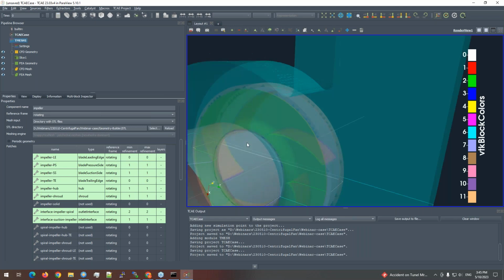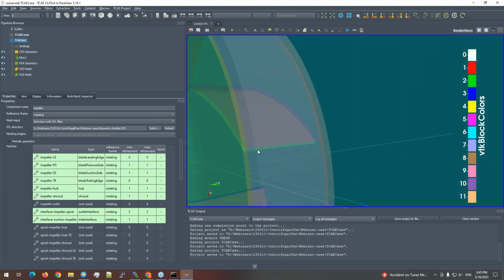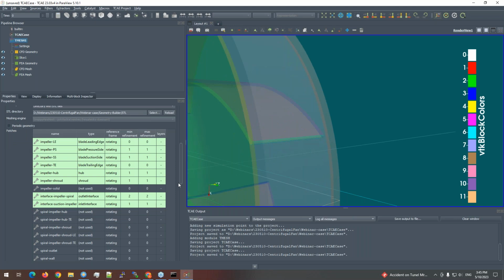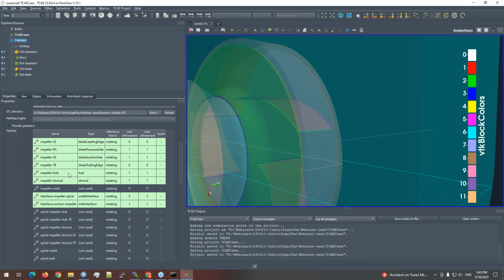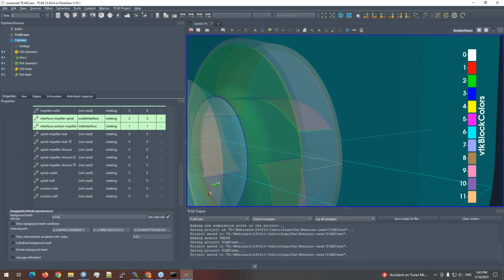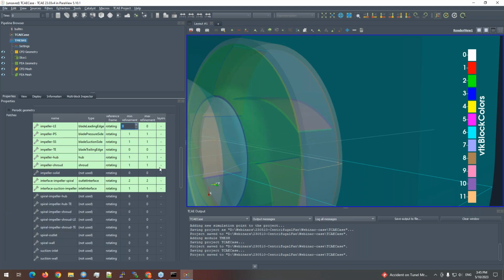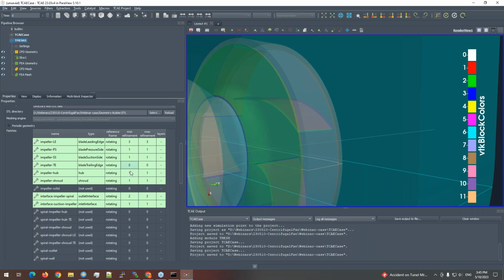And the leading edge, I think here the thickness is 1 centimeter. Oh no, 1 millimeter. Oh, I am not sure right now. No, I think 1 centimeter. Yeah, 1 centimeter. So I will set the level of refinement because I have 2.5 centimeters, to have several cells here. So I will set level 3 for the trailing edges.